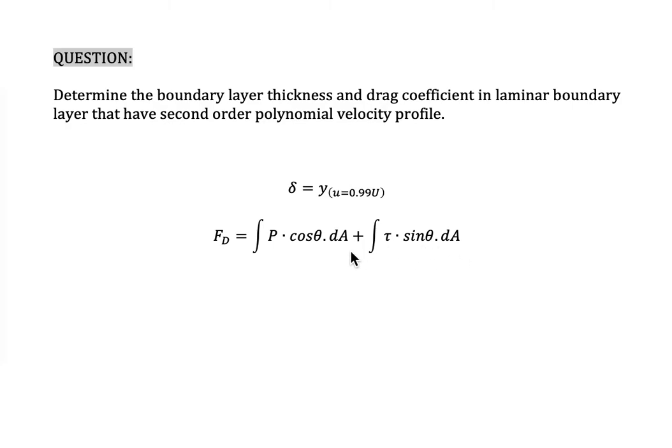If we see this equation, we find that pressure can be measured directly. Usually people measure pressure by putting a pitot-static tube probe on a flat surface, and then we can measure the pressure on the surface. Cos theta can be measured, because we can measure the inclination of that surface. A is the area for sure: we have a flat plate, and we can measure its area.